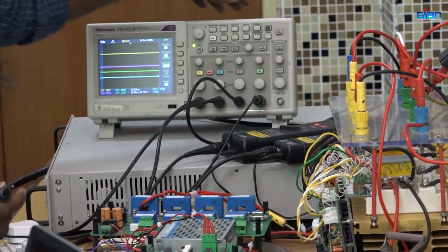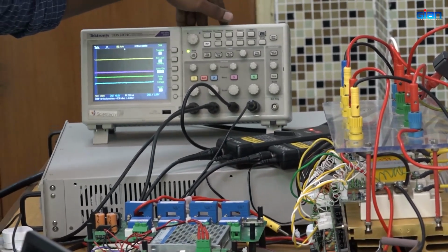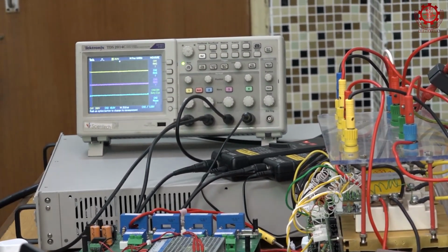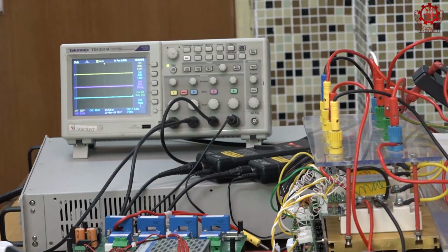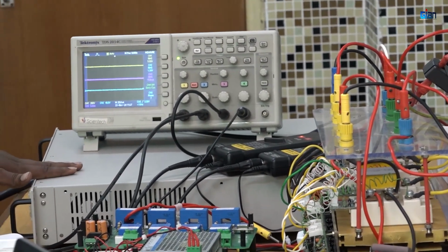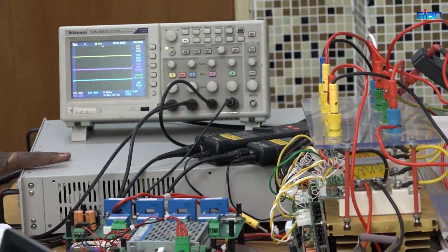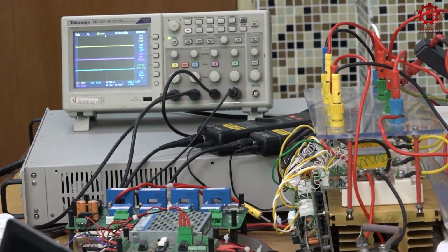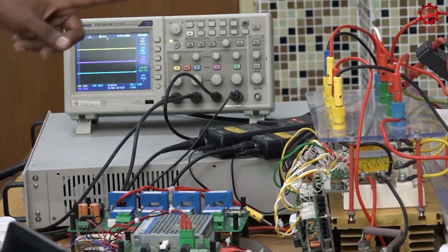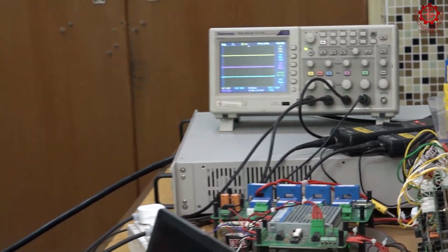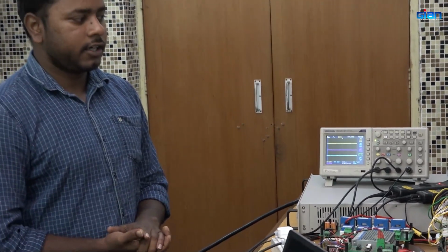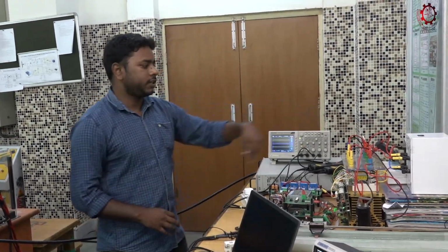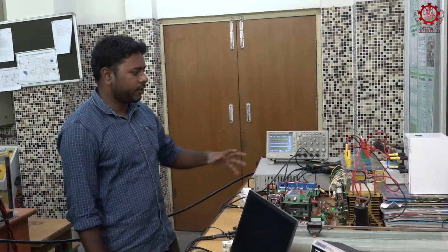So now we will see whether our setup is working or not. As I previously told, this is the power supply which I am using. This is the load resistance. This is the high frequency transformer. As we know, the DAB is the isolated converter, so these two bridges are connected with an isolation transformer. This is a 20 kHz isolation transformer, 300 volt to 48 volt, and the turns ratio is 6.25. And this is my external inductor. So we can see the leakage inductor, where the power transfer will depend upon this one.